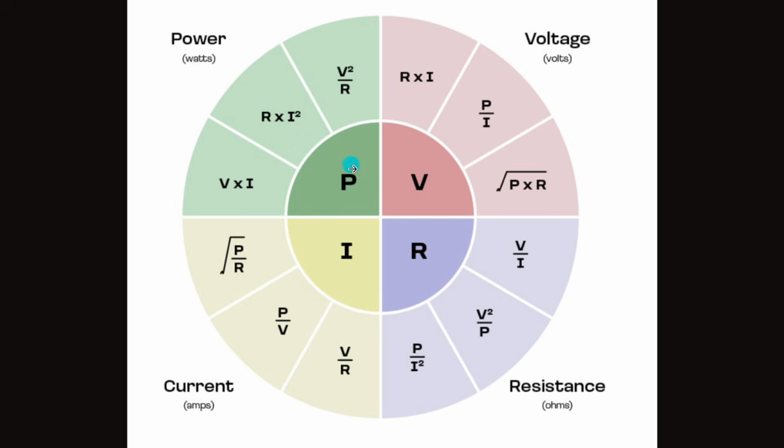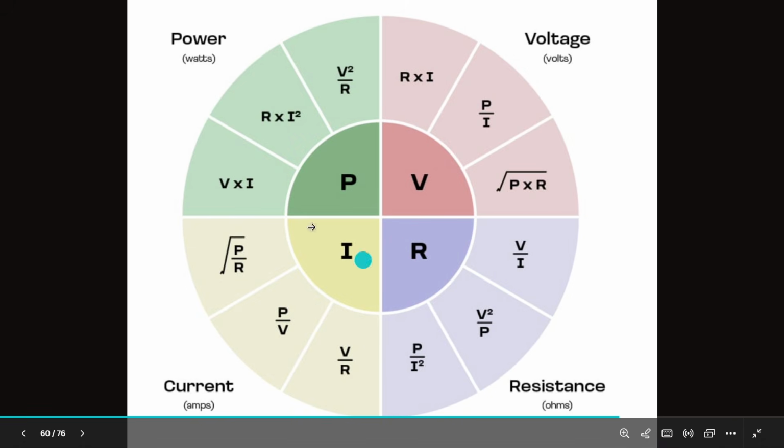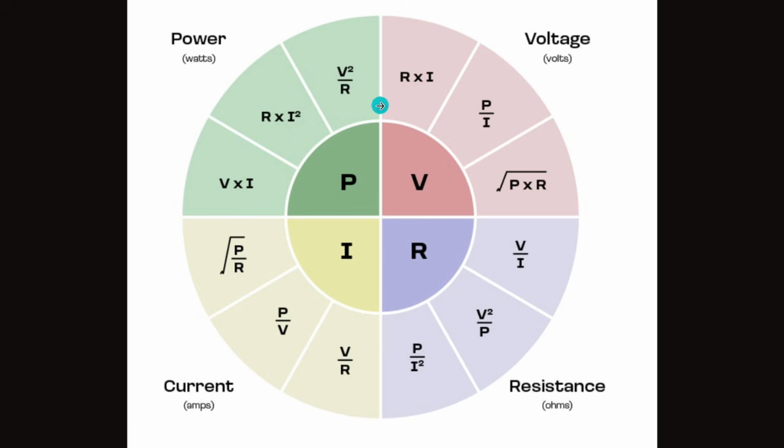And I will draw your attention to the power formulas. The typical power formula, which we will often use when we know the RMS voltage, is voltage squared divided by the load, and we can get the amplifier power. Then you have all the relationships, and you can do different types of calculations. But this is an important formula for you to remember.